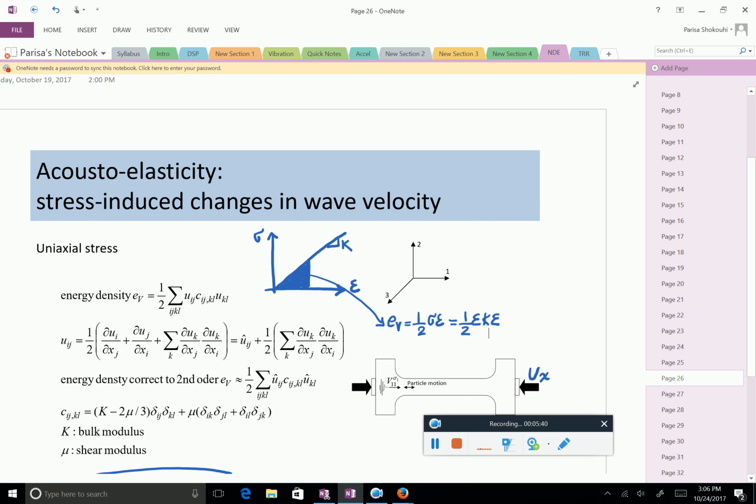So there is a theory which is called the acoustoelastic theory, and I just want to show you a glimpse of it. In the uniaxial case, if everything is in one direction, if you are applying a strain field uppercase UX, and I'm shooting with a P-wave transducer from one side to the other, where the particle motion is in the direction of loading, I want to see how I can understand why this velocity would change.